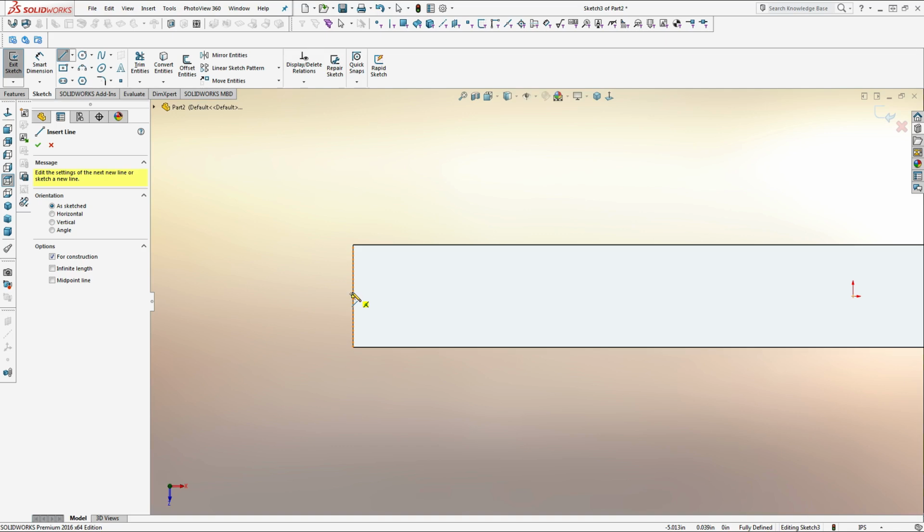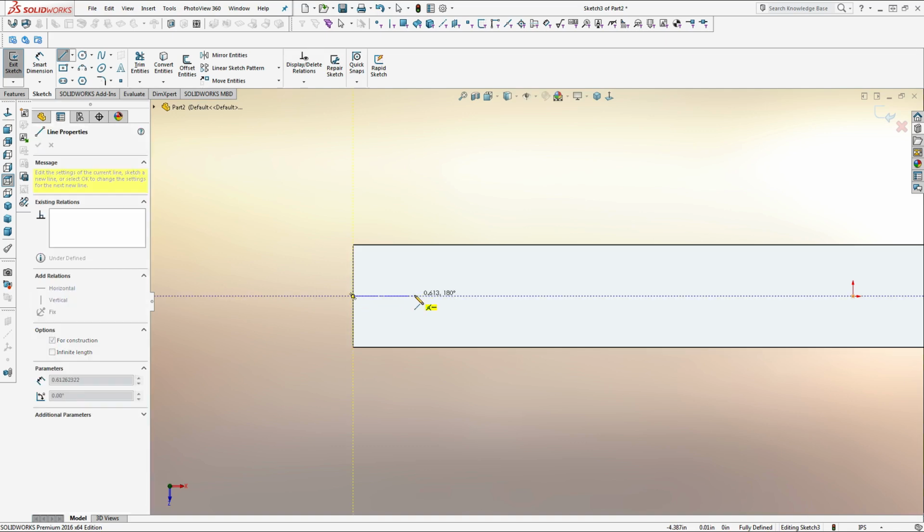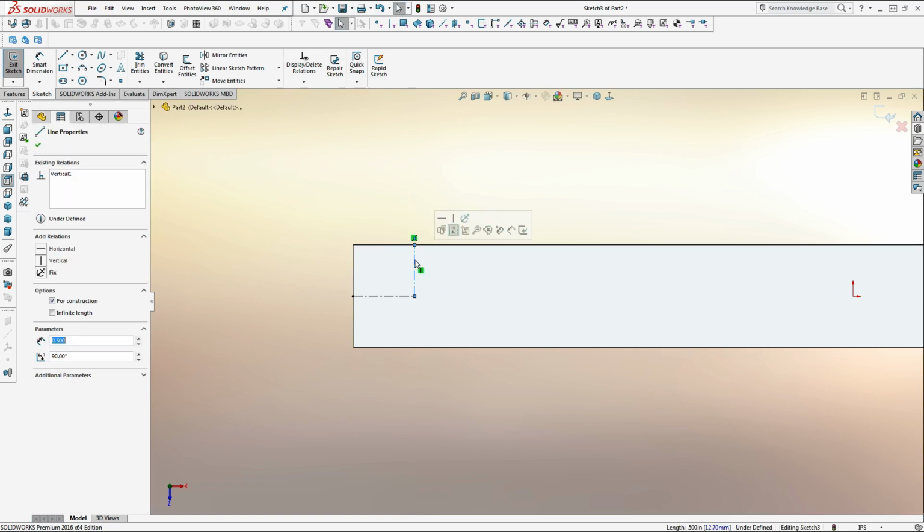So what that means is I know that this entire tube is 1 inch in length, or sorry, 1 inch in width, and that it's conveniently giving me that yellow dot there, which is a halfway point. So that halfway point is exactly 1/2 of an inch, which is the exact spot I want my hole in the x-axis. So I'll just use that as a guideline. Now I know also if I put a line up to the top, that line length is going to be 1/2 inch.